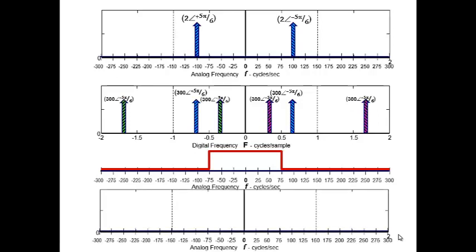So when I multiply this spectrum by this spectrum and we filter it, only these two center impulses come out. Their amplitudes get scaled back down to where they were. But notice they're at a different frequency and the phase isn't the same. Phase sign flipped. That's the punchline. That change in frequency, that's the aliasing. The aliasing came from making these spectral copies. And by keeping track of the phase as part of the process, we see which one, the positive phase or the negative phase, ended up over here on the positive side.